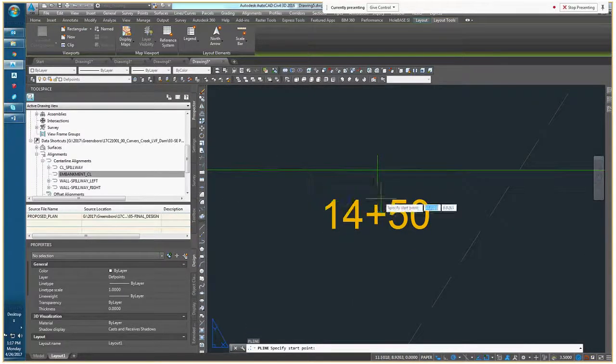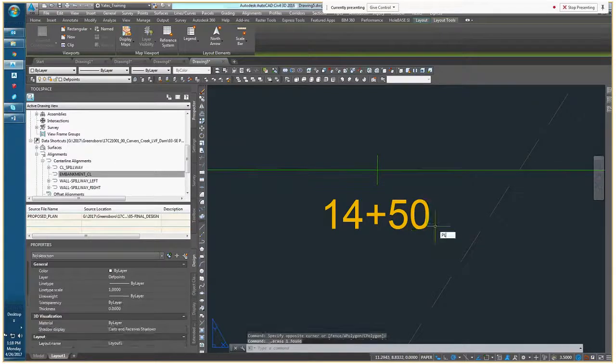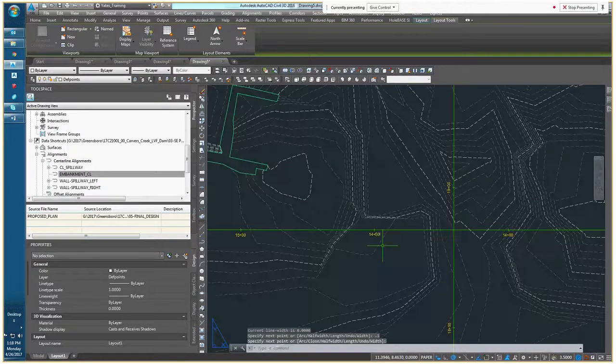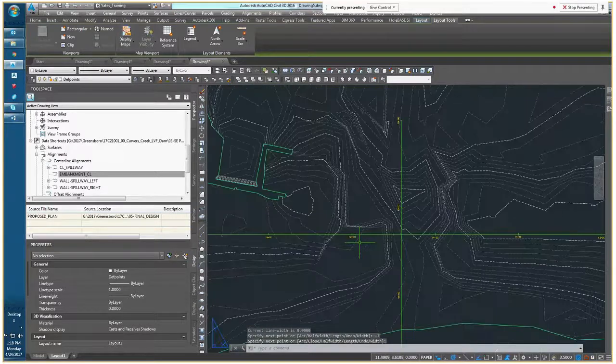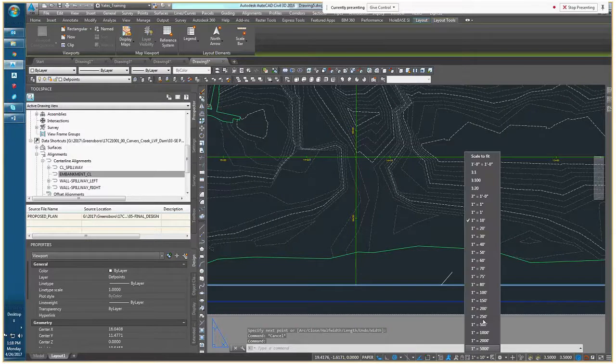So, for instance, let's see here if I can draw this. Turn off O-snaps. What I'm going to draw here is just a quick reference line telling me that I know the height of this text is supposed to be 0.1, so I'll start a polyline up here and draw it down 0.1. This is just sort of demonstrating what's happening here with the annotative, automatic annotative scaling.